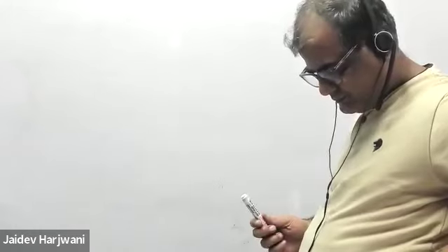Here, if we have an RC network cascade and use 6, there will be a 180-degree phase shift, and again the common emitter will have 180, right? In the question, they are cascaded together and connected to a common emitter amplifier. That is correct. So 180 plus 180 will become 360.